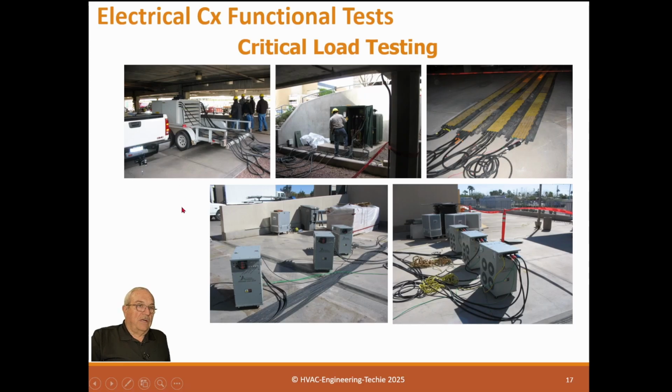Here happens to be a hospital. This was a hospital data center. You can see we had a main panel here on the main transformer. That was one test, and then we had another test on the PDUs of the data center. And the reason this gets expensive is not only do you have to rent power sources here, the load banks, but you have to wire them up.